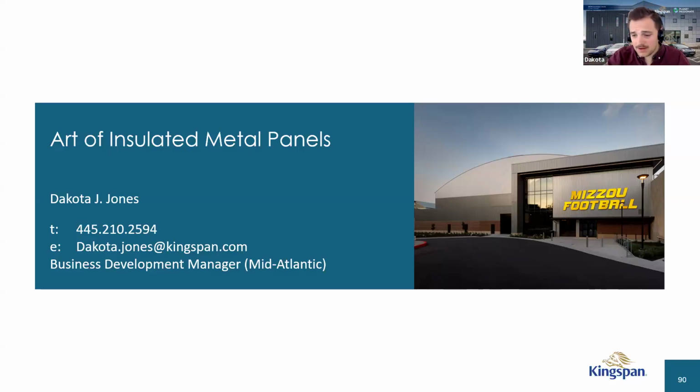It's all third-party verified. For those less aware of what NFPA 285 is, it's an assemblies fire test. It kicks on when we're doing rain screens. We call it a carrier panel, the rain screen panel we were talking about. It's essentially an IMP with an integrated hat channel. That's where the NFPA 285 is going to be, so look up carrier panel.